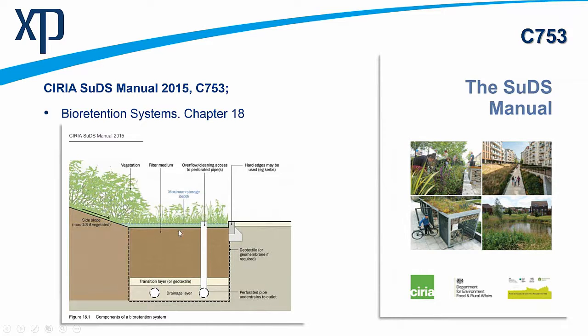Some will seep down into the subsoil, and we put in a filter media down below. So down below this shallow depression, we would put in a layer or layers of filter media feeding down to a drainage layer at the bottom. They don't have to be particularly deep, and this drainage layer would comprise a bedding stone and maybe a perforated pipe. It may or may not have a pipe to discharge away.